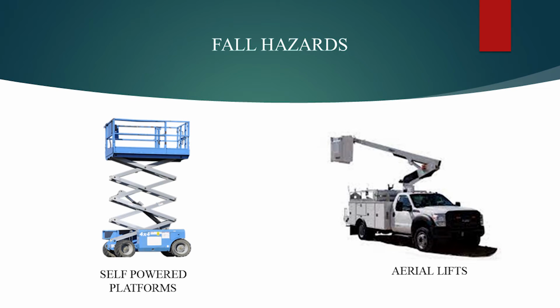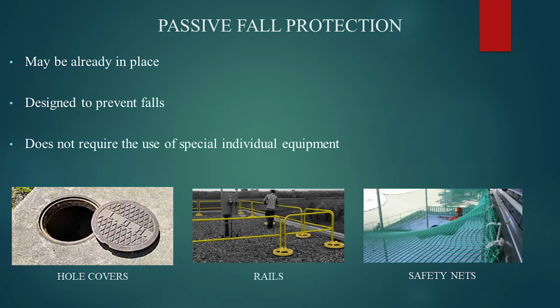Working from a raised vehicle surface is also a potential fall hazard, including any vehicle-mounted device, telescoping or articulating, or both, which is used to position personnel. Some examples are extensible boom platforms, aerial ladders, articulating boom platforms, or vertical towers, also known as scissor lifts. Whenever performing work at 4 feet above a lower level in one of these vehicles, fall protection is required. For more detailed information, refer to the TUSD Aerial Lifts and Elevated Platform Safety Program, or OSHA General Industry Regulation 29 CFR 1910.